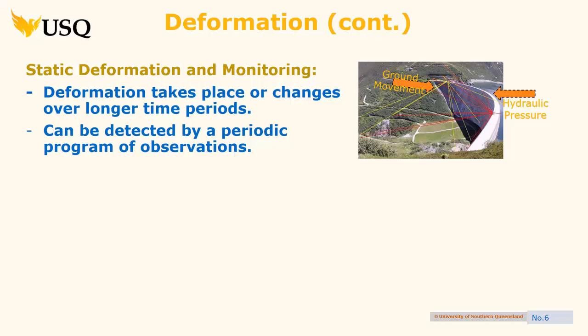Now, you saw with the tide gauge question in assignment 1, how you looked at it over a fairly long period of time. Only actually 2 people got the answer right at the end. It was hidden a bit. It's actually the tide gauge that is moving. So there's tectonic plate movement. It's not that the satellite telemetry is getting better, which it is, but it's not just that. The reason it's converging is the tide gauge is physically moving. And Zara's put a graph in, you'll see in the solution sheet, that shows you the GNSS results from that.